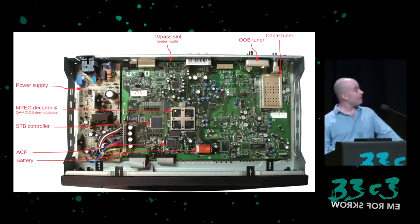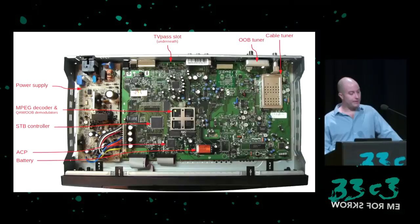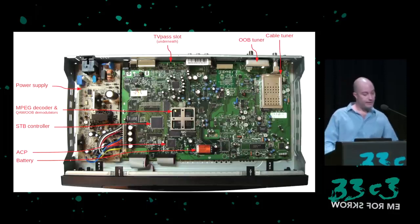Inside a cable set-top box, it's very similar to a satellite set-top box, but the cable boxes tend to be more tightly integrated. Signal enters the tuner and passes through a Broadcom chip that handles demodulation, and the same chip will also handle MPEG decoding after the transport stream has been decrypted by the ACP. A 68K microcontroller acts as the set-top box main controller, again talking to the ACP via SPI, and a battery provides backup power to the ACP and also to the non-volatile RAM used by the main controller.